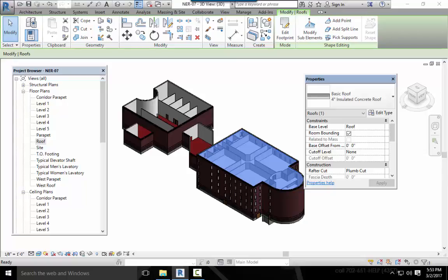So we're going to move on to the next part of the book, tapering a flat roof and adding drains. If you went through the floor procedure in Chapter 6, you'll see the process for tapering a roof is similar to pitching a floor. You may have also noticed that creating a roof system is identical to creating a floor system. To taper the roof insulation, you must first divide the roof into peaks and valleys, and then specify the drain locations based on centering of these locations.